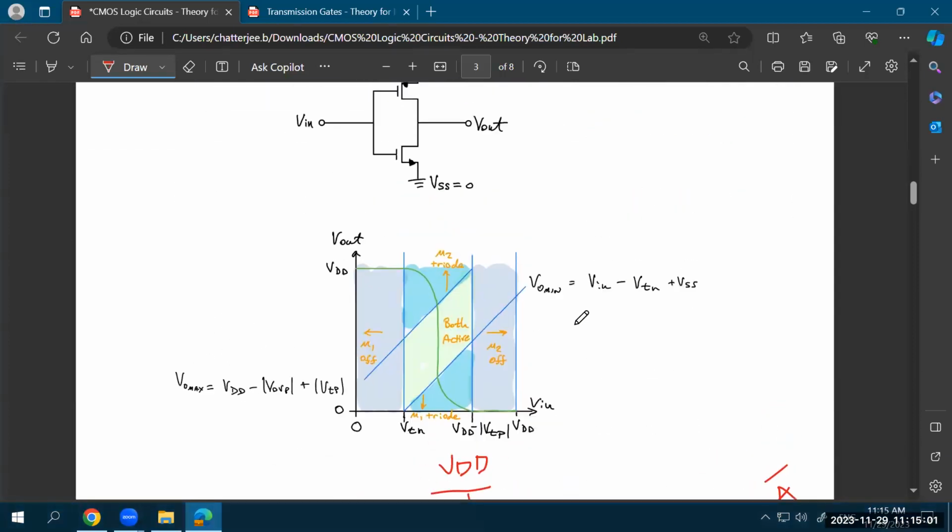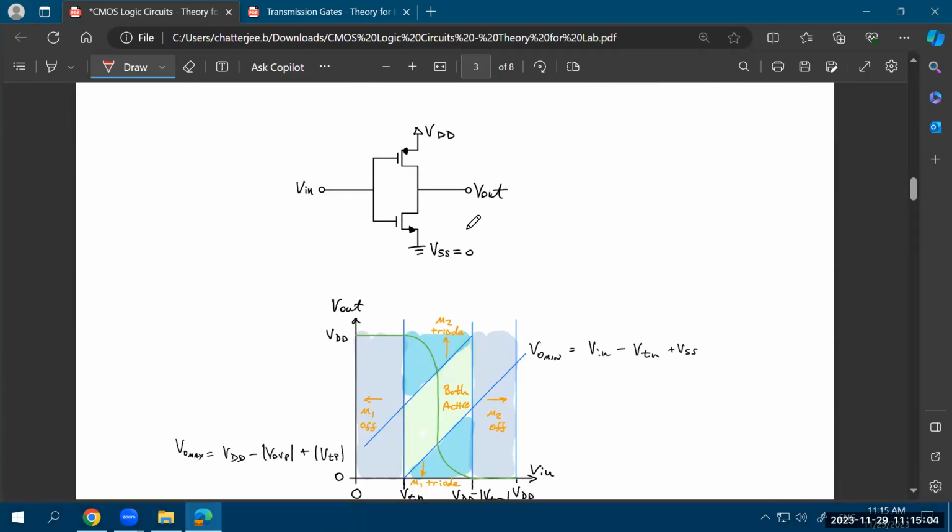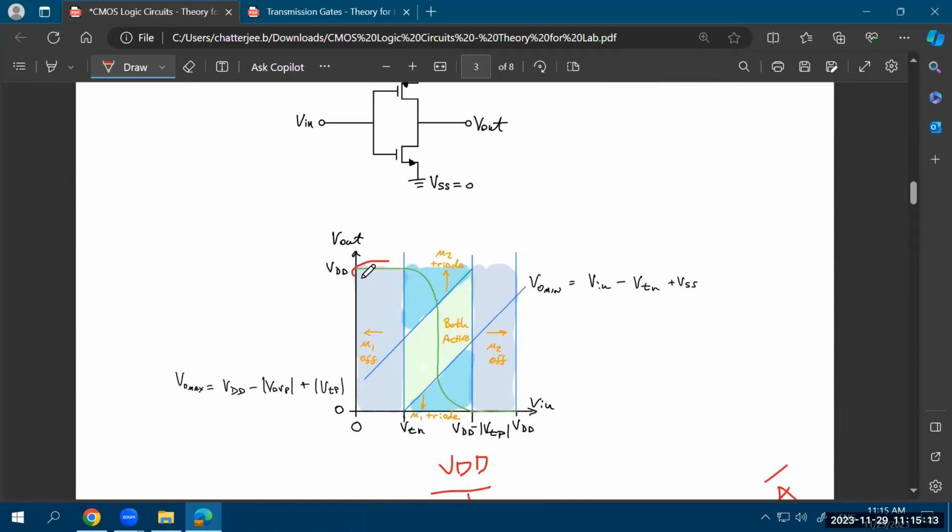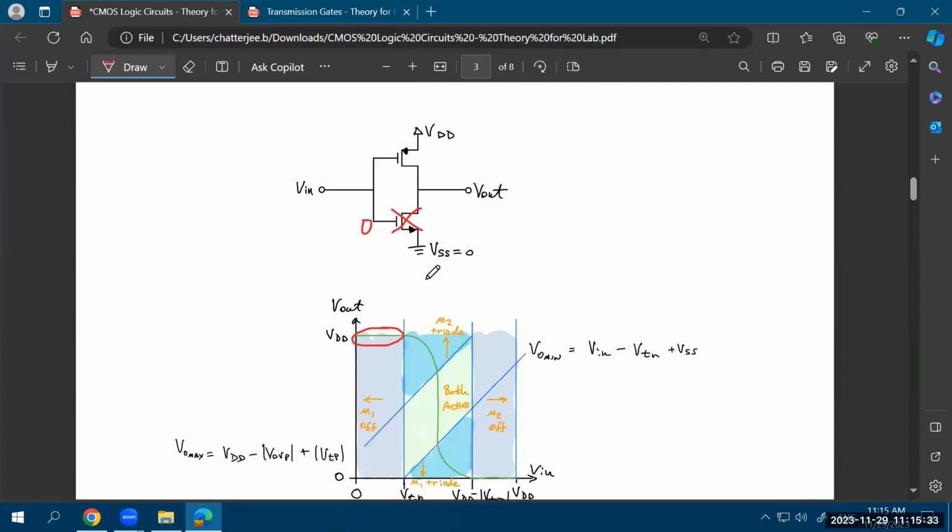Okay. So now in a CMOS inverter, what is interesting to see is that when your input voltage is very low, when your input voltage is over here, then your M1 is off. Your NMOS transistor is off when your input voltage is very low. So this is 0. When your input voltage becomes higher, or when VGS becomes higher than the threshold voltage at the input, then your NMOS turns on, and the NMOS turns on in saturation, right? Because, as you said, one device will turn on in saturation all the time.